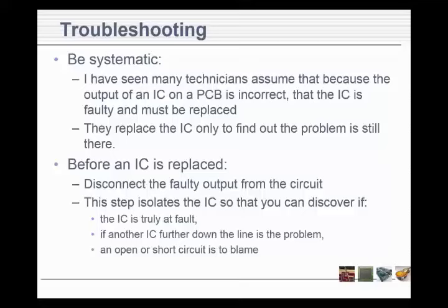And so all they had to do was desolder this one output pin and make sure it wasn't connected to anything and then test it, and if it was doing good, it wasn't this chip. It was maybe the next one down the line or another couple down the line. But there were a lot of folks I could not make see that, and they'd be throwing a lot of good chips away. So make sure that thing really is at fault before you get rid of it.